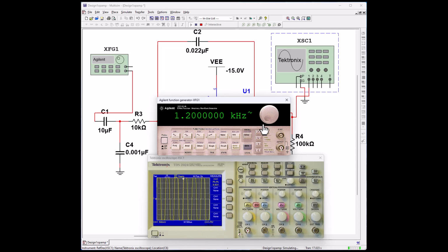We'll get that back up there to 10. Alrighty there. See if we can get it back to 7. And let's get this down so we get accurate. It's not going to let me do that, so we got 7.36. So let's go ahead and go to frequency. So we got 1.4 kilohertz is our cutoff frequency, or close to that.